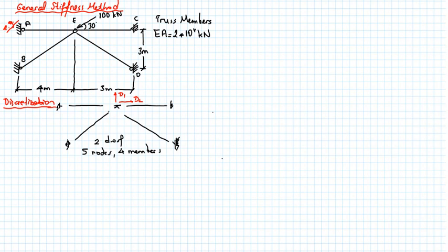And here, of course, by its nature, we don't have any member loading. All the nodes must be joint loads and applied to the nodes. That's the definition of a truss structure. So basically, all the loads here will be unbalanced forces for us. And if we do determine the force vector, I don't have to do superposition because I can directly obtain what the unbalanced forces are. We don't have any fixed end forces.